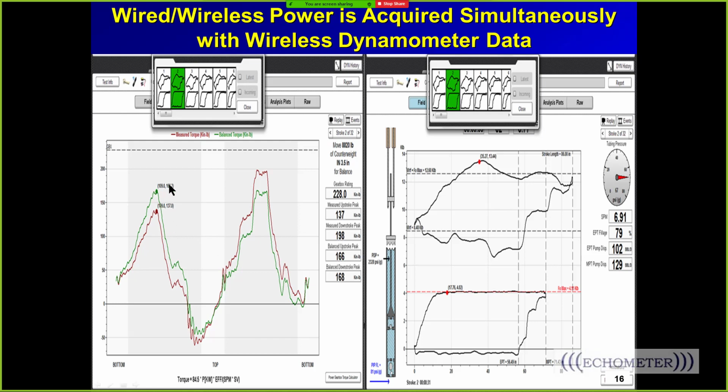This is again the same well, the V11 well, and this data is an example that we have. We'll go through this. We look at stroke number 2, it's full, and then the pump fillage changes. As the pump fillage changes, the rod load changes, and the net torque on the gearbox changes. So it's important when you position your weights to position the weights for the normal pump fillage.